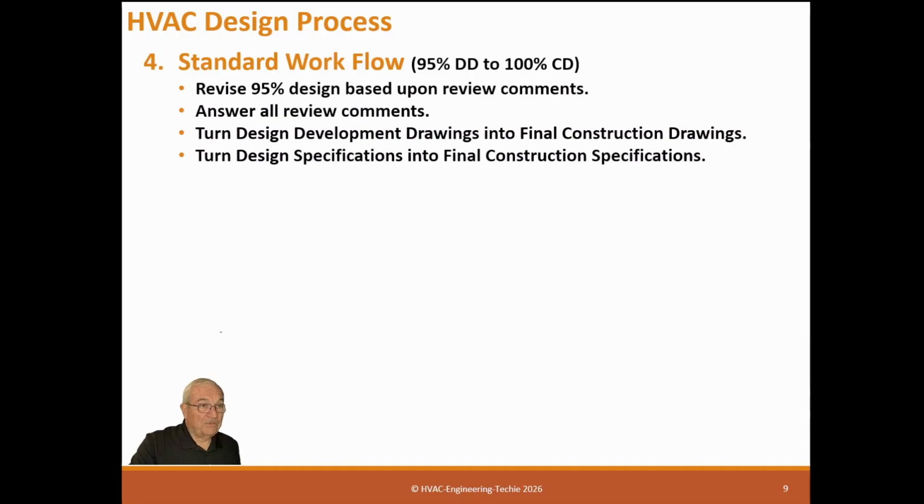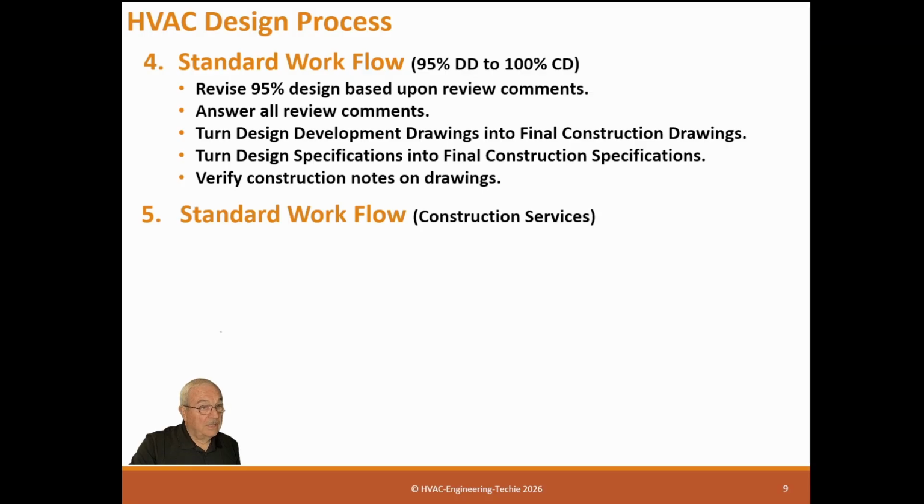It's easy when everything is digital. Turn the design specifications into final construction specifications. Verify construction notes on drawings. You make sure, and one thing I always complain about is, I know we're all trying to make money and we're trying to, in a hurry, do things, and we use a lot of standards. But make sure your standard notes and standard details actually match this project.